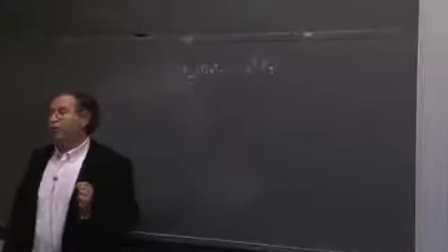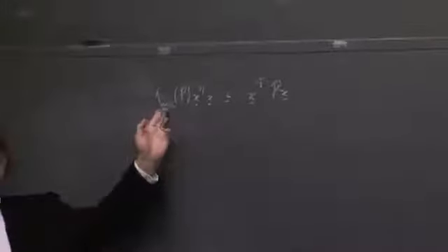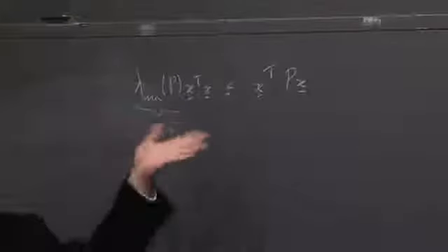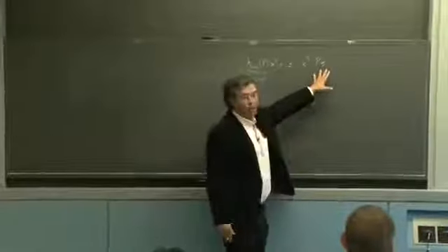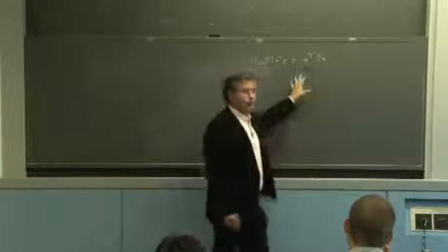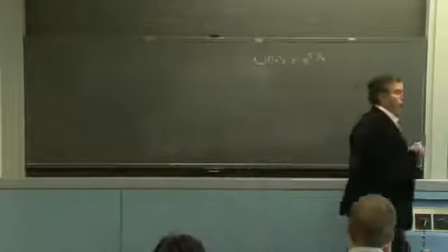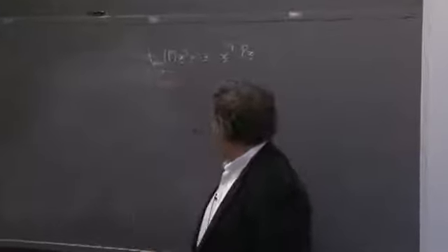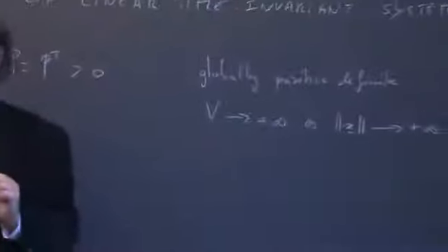We said that in the general case. And therefore, since P is a positive definite matrix, this lambda min is going to be strictly positive, and therefore x transpose Px will tend to infinity as x tends to infinity, using this bound on x transpose Mx we talked about last time. So if we apply it here, using this left part of the bound, we get this, and this is strictly positive, and therefore this second radial unboundedness property is going to be verified.